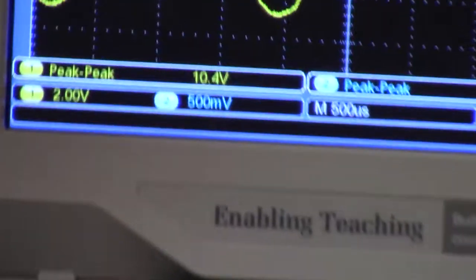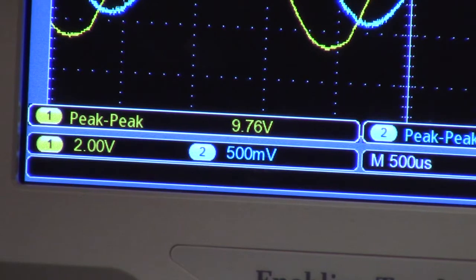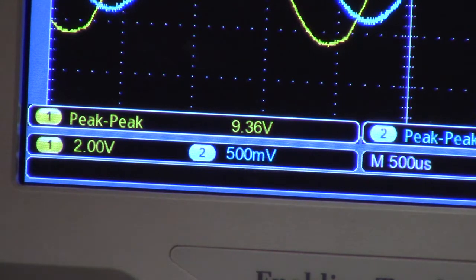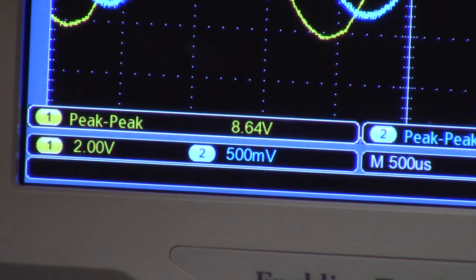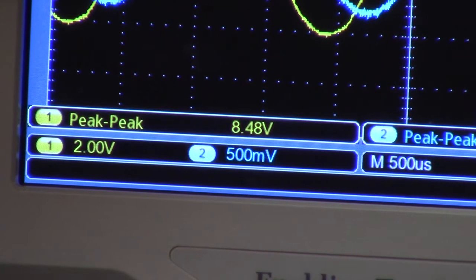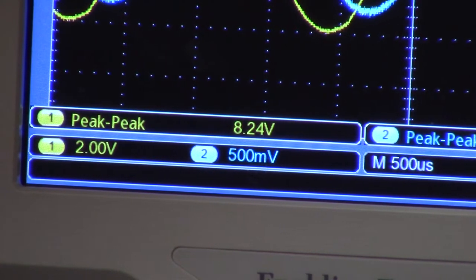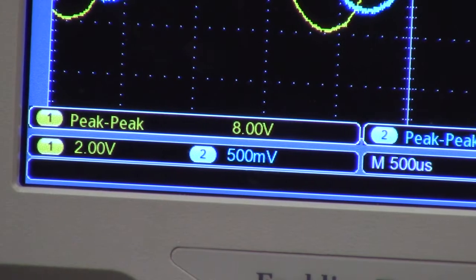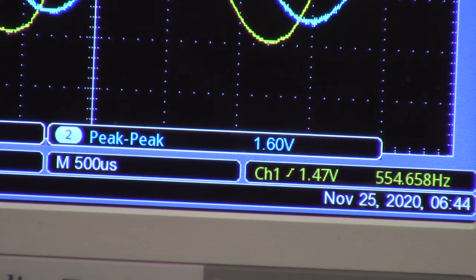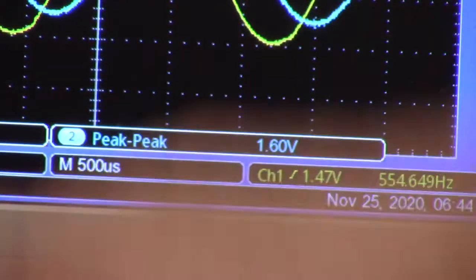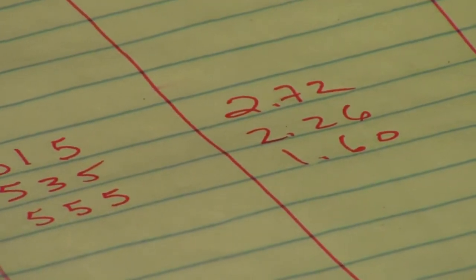Okay, so let me adjust the voltage, because again, we want to see the current change, but the whole point here is to see the current changes because we're at a different frequency, not because the voltage changed. And of course, both of those do affect it. And so that's why I need to keep it at 8, and like I said, sadly this changes its voltage because of the internal resistance inside of it. Okay, so this says 8, good, and now I can take a measurement of 1.60. So you can see how quickly it's dropping, right? Look at that. It's already dropped quite a bit.